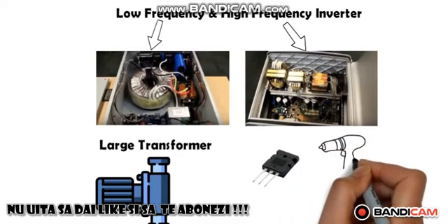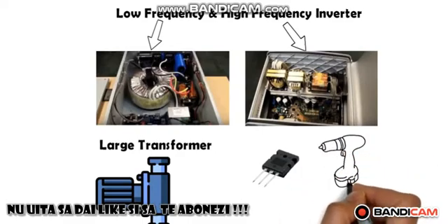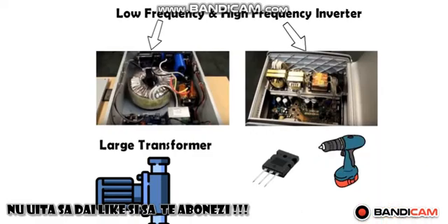High frequency inverter application is appropriate for a wide variety of uses like tools, battery chargers, small appliances, AV and computers. High frequency inverters make up the large majority of inverters available in the retail market. High frequency inverters are also available in lower power categories such as 300, 600, 1000 and 1500 watts, etc., as opposed to low frequency inverters with their power levels normally within thousands, typically 2000 to 3000 watts.